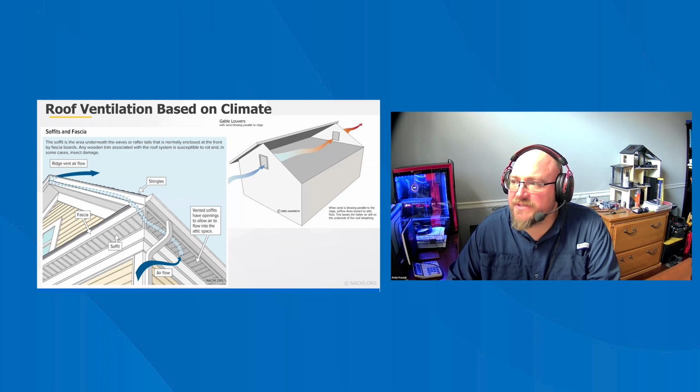In stick-built roofs, some builders install an additional top plate across the top of the ceiling joists at the eave to raise the roof height. This additional top plate raises the roof height, prevents compression of the insulation, and allows room for ventilation. Most building codes require roof vents to expel moisture that could cause insulation or other building materials to deteriorate during the winter. In summer, ventilation may reduce the roof temperature and lengthen its service life.